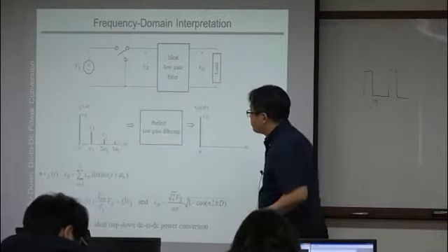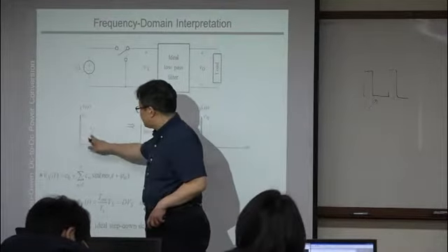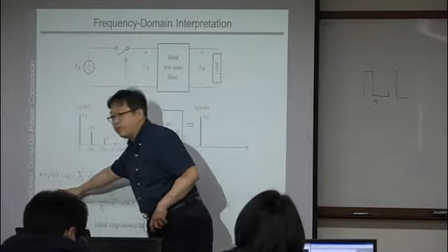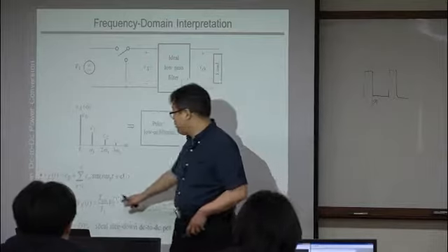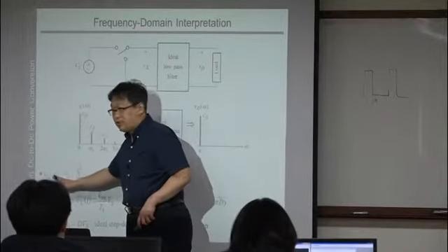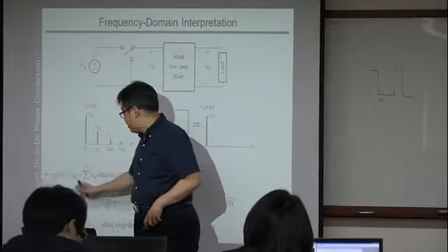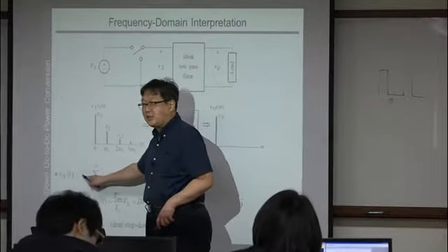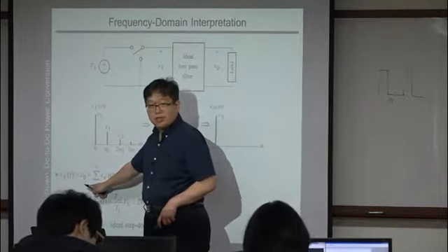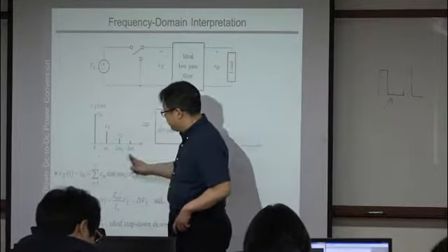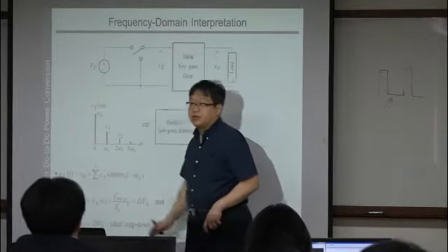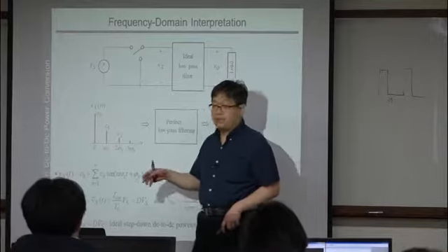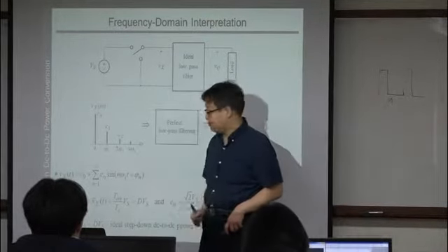And here, this expression can be simply modeled like this. Vx, that is the time domain function, and here C0 is the average waveform. That is the voltage you want, right? Then the rest of the terms model the harmonics, I mean the switching frequency harmonics.